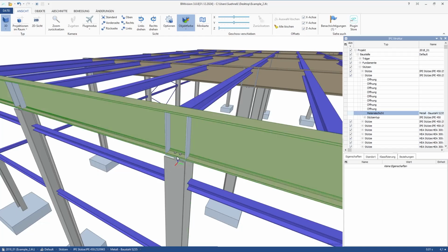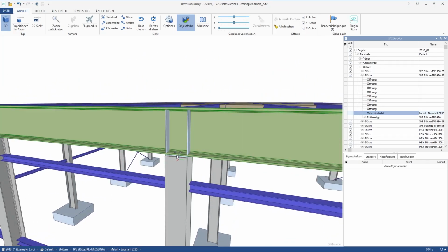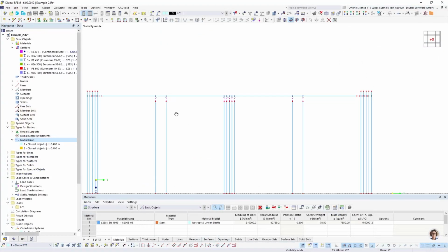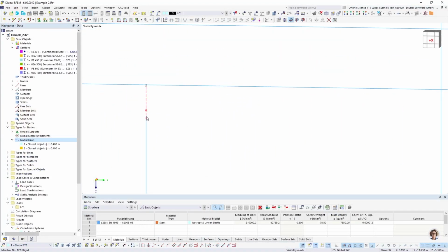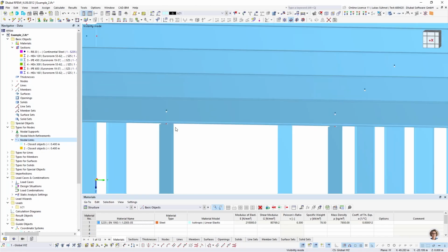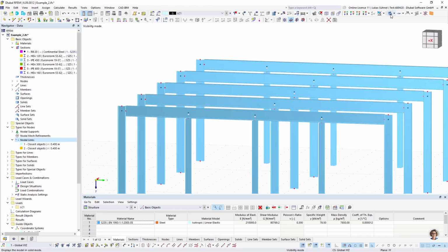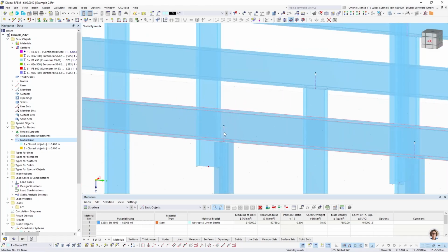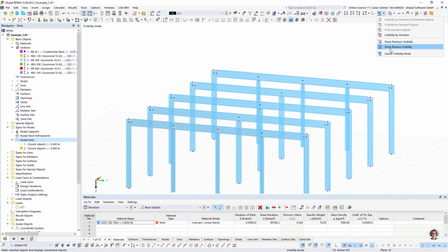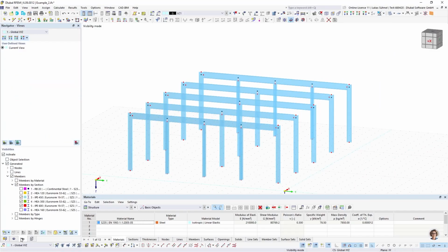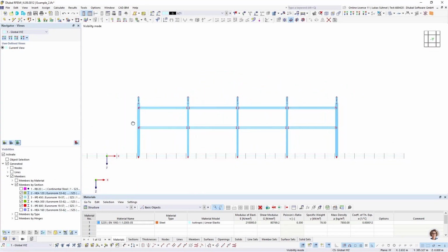We could argue if we want to place it on the start of the nodal link or at the end. More correct, it would be probably even at the start of the nodal link. So down here, because we have some kind of a lever arm between the lower flange to the center, but well, we simplify it a bit to avoid torsional moments. So now we also have these nodal links here. And I will simply continue. What's next? Maybe, no, not those. The coupling members in the walls.